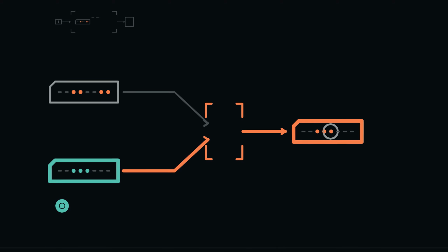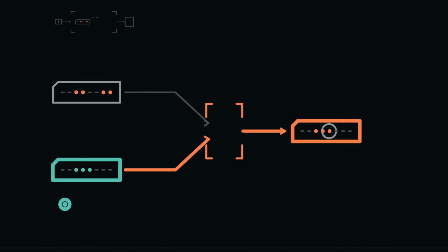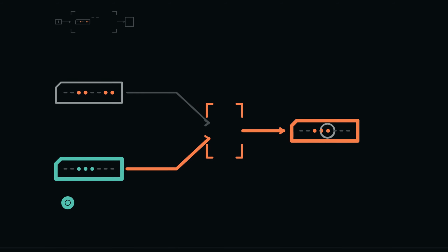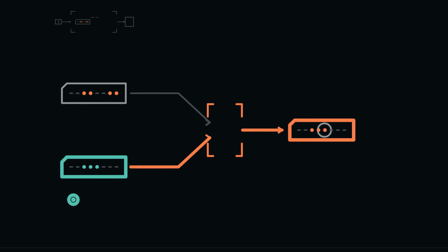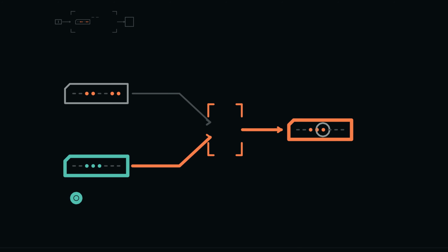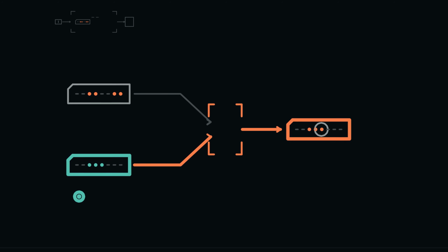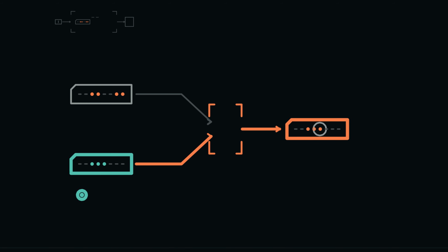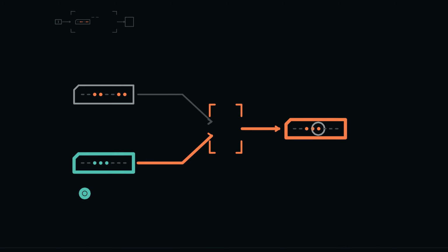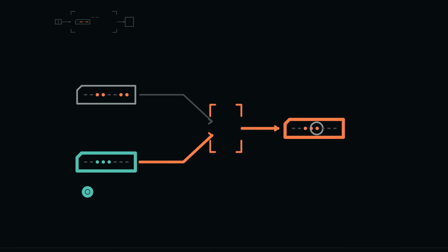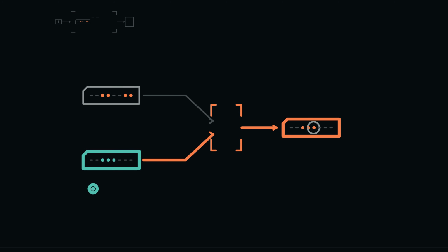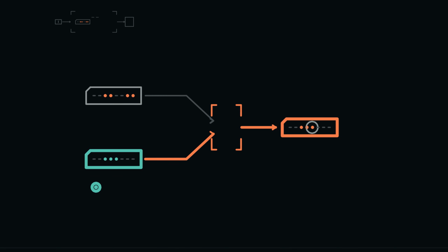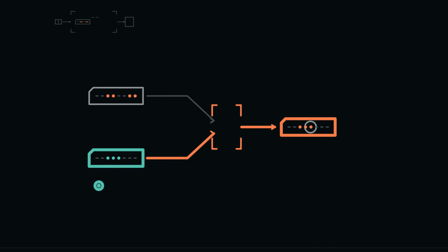Do not confuse a selector with a decoder. A selector chooses one of several data candidates and produces one data output. A decoder receives a coded selection value and activates one of several choice lines. Railway language can make both look like routes, but their contracts point in opposite directions. Many data inputs toward one output for the selector, one coded input toward many mutually identified outputs for the decoder. We will build the decoder when memory needs one address to choose one location.